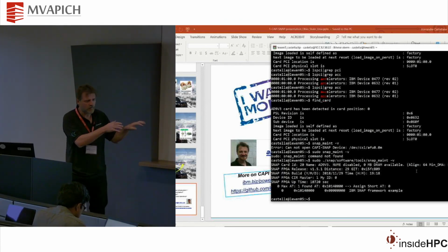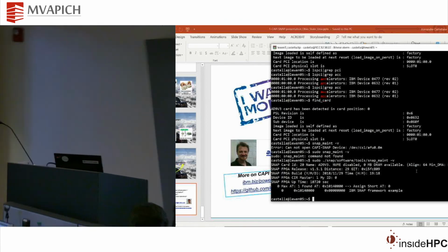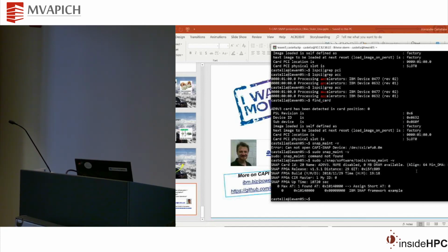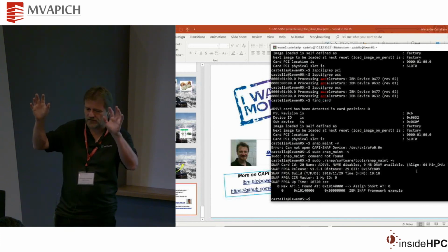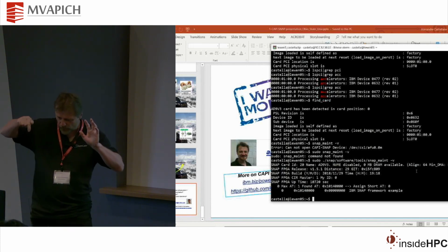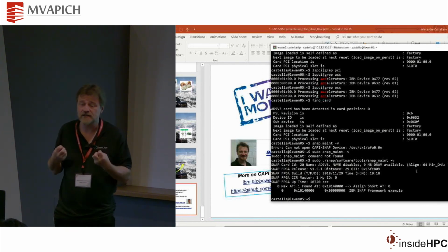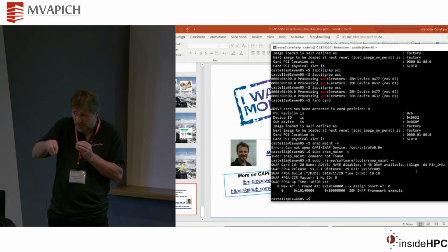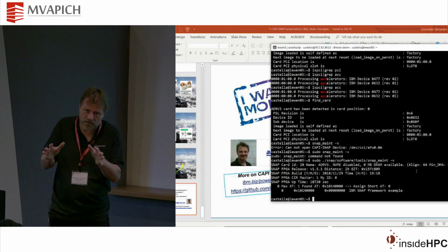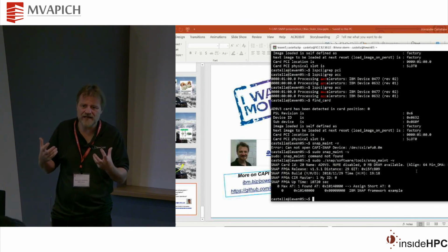We can do it offline, but I can reload a new binary that I have prepared for you to take into account. When you have made all your C++ writing and so on, simulation, everything is okay, when you push the button to create the content of the FPGA, which will be stored in a flash, it takes about 1 or 2 hours. But you really build a chip.